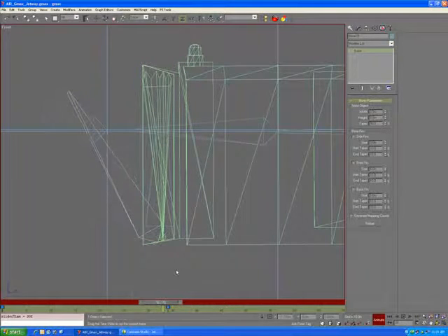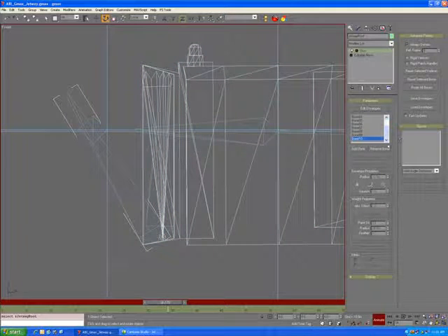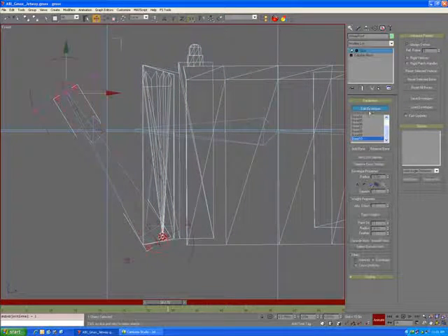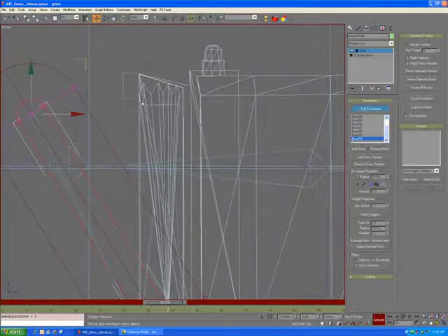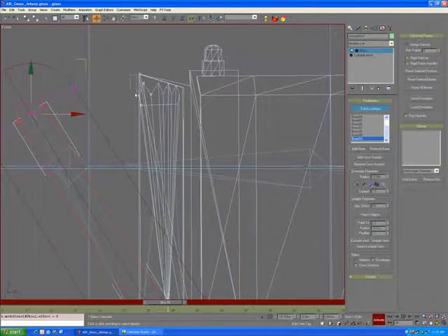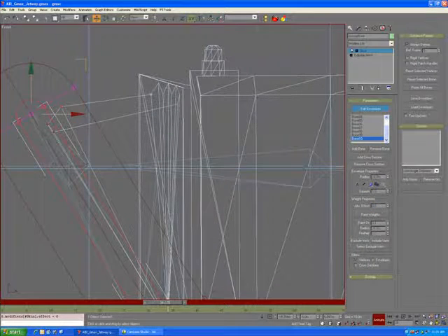So now what you can do is you can go to that keyframe, you can go back into your skin, and now you can actually edit the envelopes for that bone. So if we select these right here, let's just give them a value of 1. So now it's going to stretch them way out. So now we can grab these and go, say, 0.85, and you just start to go in and 0.7 and make the jetway stretch.